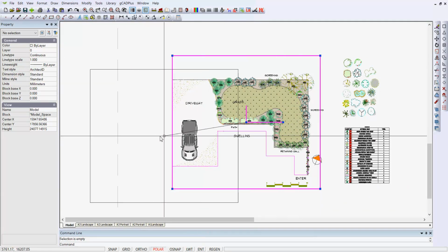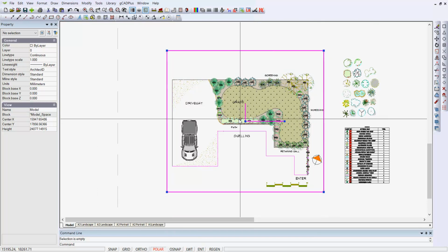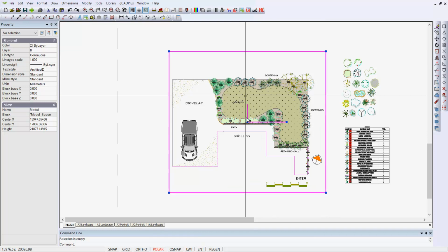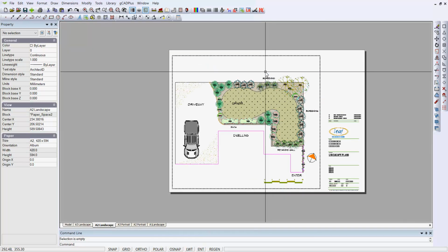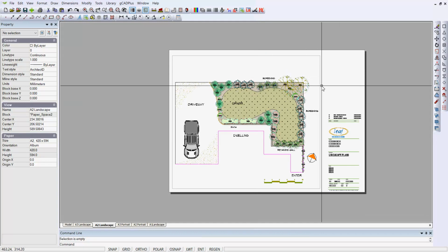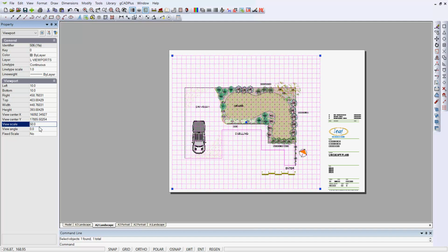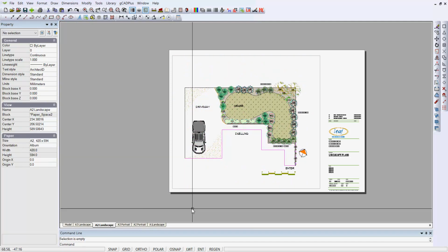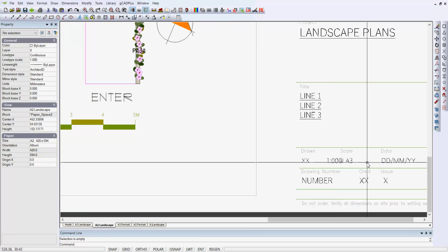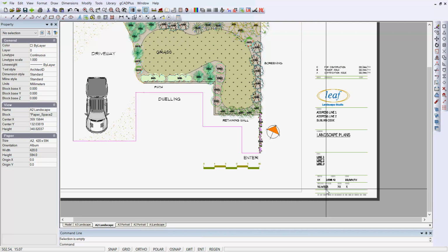I'm just fine-tuning things. I want to make sure that everything on the site is displayed at maximum resolution, maximum view, if you like, for the site. I'm relatively happy with that. You could tweak it further, but that's on an A2 sheet, and it's a view scale of 43. And if we wanted a fixed scale of, say, 50, we could do that, and then we could say fixed scale 50. So we could come in here now if we wanted to and edit this site information and change that.